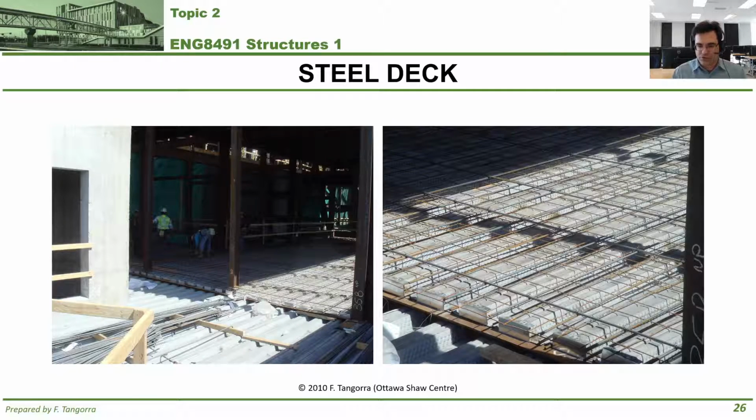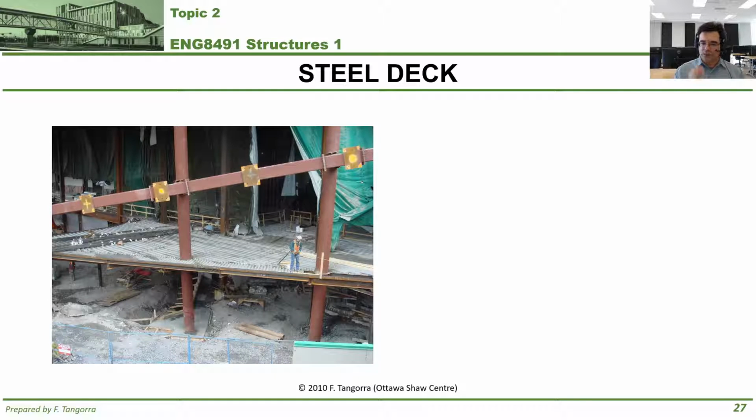So this is what happens. After you put the deck in place, you would put reinforcing steel parallel and perpendicular to it. You would cap off the openings in the deck so concrete doesn't get inside that decking and under it, and then you cover it with concrete.